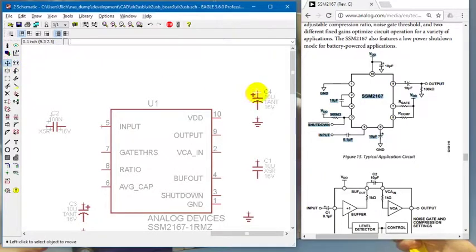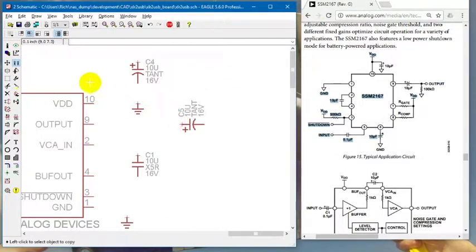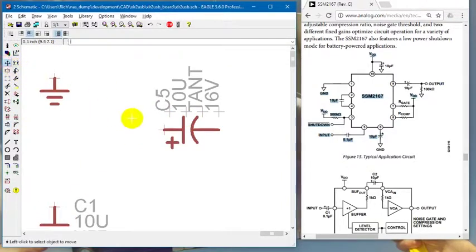polarized capacitors, and he's sideways, so it's another opportunity to use the smash command. Set it sideways, smash. Eagle has some strange words for a couple of things there. Smash and rat's nest and a few other things like that. So, you may have noticed this before. When Eagle gets confused because you're too close to two things, it'll highlight the one that it wants to use. So if you ever click on something and it turns a really bright color and you don't know what it's doing, it's asking you, do you want this one or do you want something that's kind of close nearby? So it's trying to help you out.